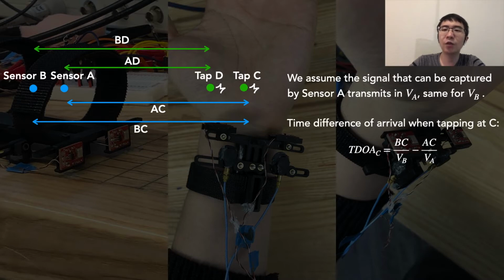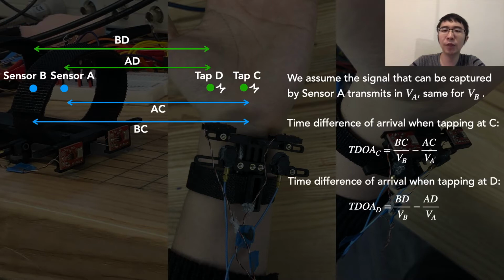With that, the time difference of arrival between sensor A and sensor B when tapping at C should be BC over VB minus AC over VA. Similarly, the time difference of arrival when tapping at D should be BD over VB minus AD over VA.